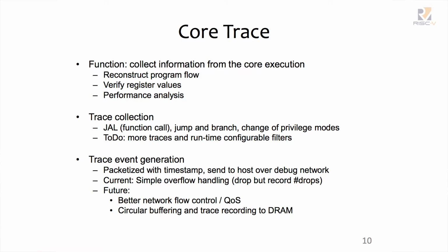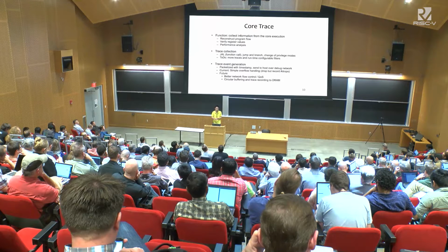The usage for that is you are enabled to reconstruct your program flow from these traces. I will show some examples afterwards. Currently, it's only extracting information for function calls and jumps, but in the future, we hope to extract information like load and store, and special instructions if any instruction is trapped, and allow you to set different filters to decide whether or not you want this information to be extracted to the host computer.